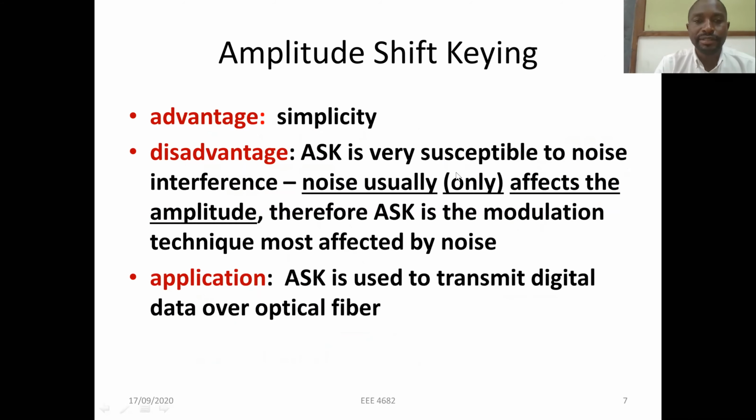Usually, whenever there's a change in the value of the amplitude, it makes the system prone to noise. You can, however, apply amplitude shift keying to transmit digital data over optical fiber. It's quite useful in that area. Next, I want us to talk about frequency shift keying.